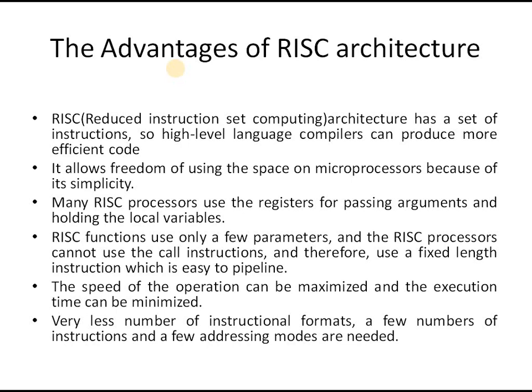RISC functions use only a few parameters, and the RISC processor cannot use call instructions and therefore uses fixed length instructions, which are easy to pipeline. The speed of the operations can be maximized and the execution time can be minimized. Very few instruction formats are needed, as a small number of instructions and few addressing modes are needed.